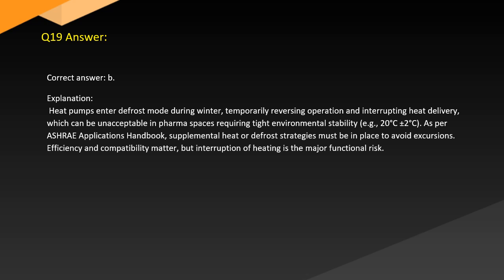Answer. Correct answer: B. Explanation. Heat pumps enter defrost mode during winter, temporarily reversing operation and interrupting heat delivery, which can be unacceptable in pharma spaces requiring tight environmental stability. As per the ASHRAE Applications Handbook, supplemental heat or defrost strategies must be in place to avoid excursions. Efficiency and compatibility matter, but interruption of heating is a major functional risk.